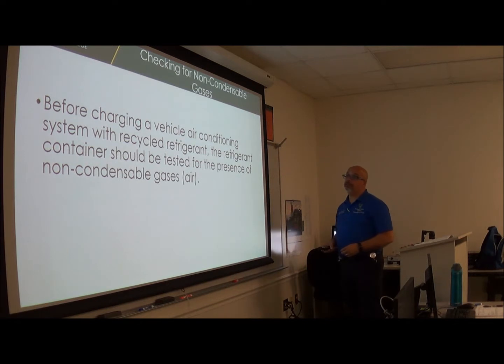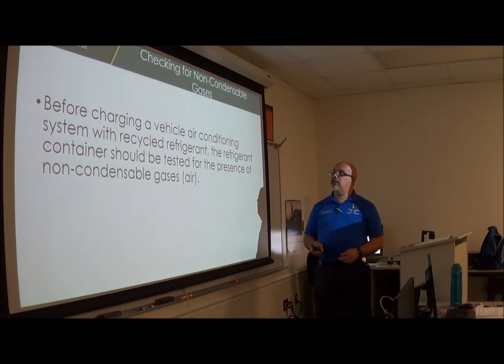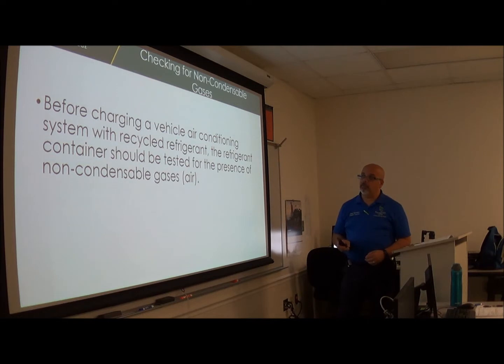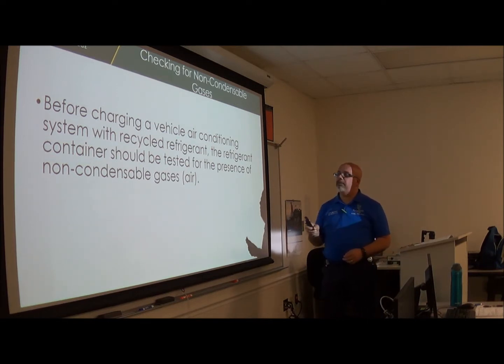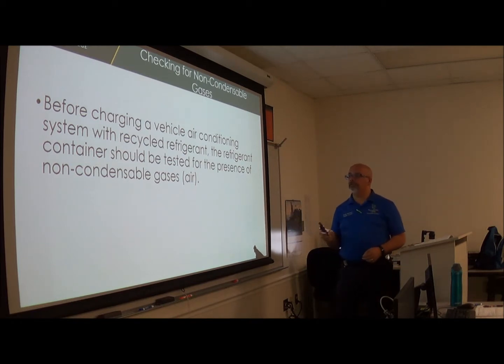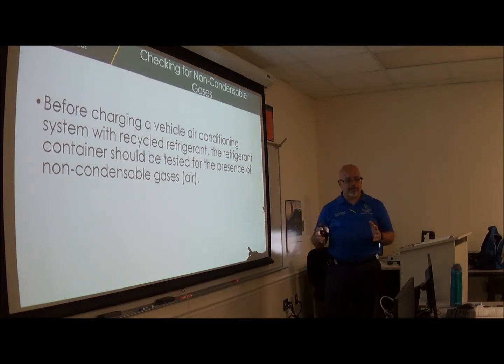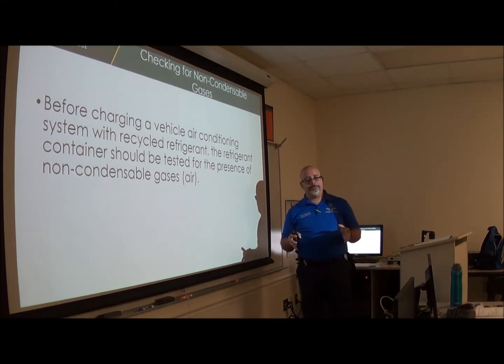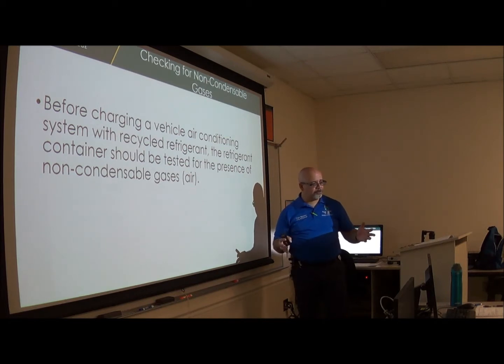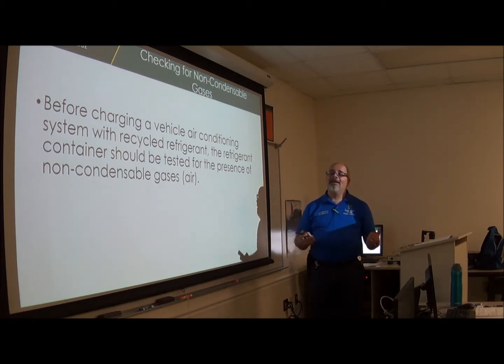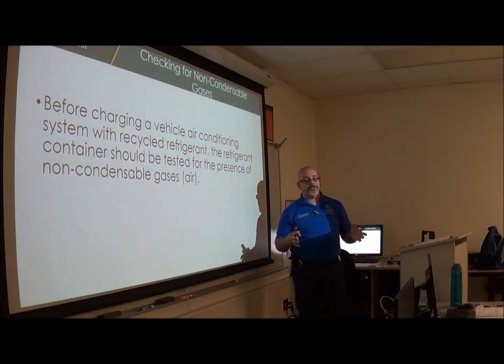Checking for non-condensable gases. Before charging a vehicle air conditioning system with a recycled refrigerant, the refrigerant container should be tested for the presence of non-condensable gases or air. Okay? There is a special equipment that you can buy, which is then another $1,000 that you would have to spend on another equipment. And that equipment determines what type of refrigerant you have there and if it's contaminated or not.